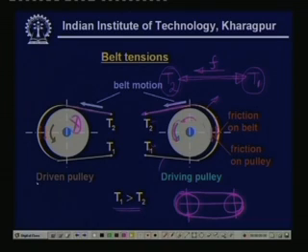So, this driven pulley, what has been written in this color, you can see this arrow means that it is creating a motion, and driving pulley means this is actually creating a motion. No, I am sorry, it is already in motion due to a prime mover. So, once again if you look at the entire situation, you have a tension on one side, tension on the other side, and the friction force. So obviously again you find this is T2 and T1, and thereby T1 is again found to be greater than T2.